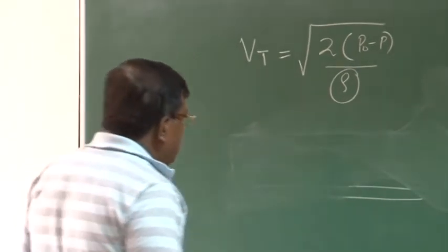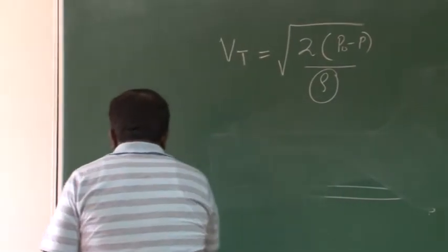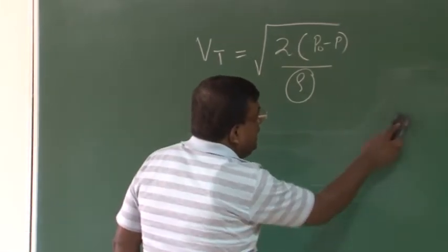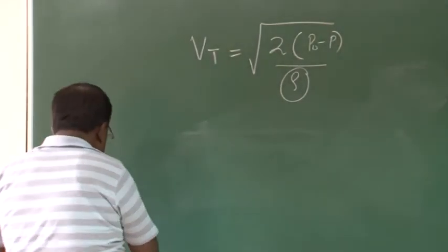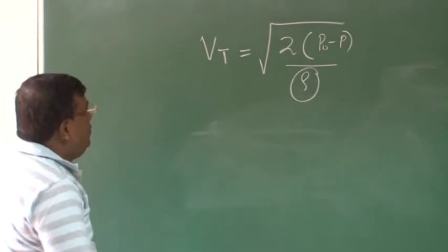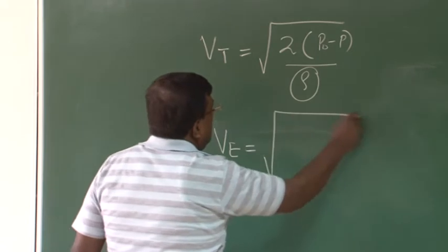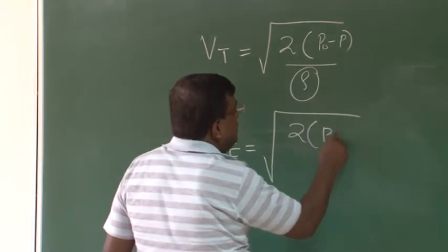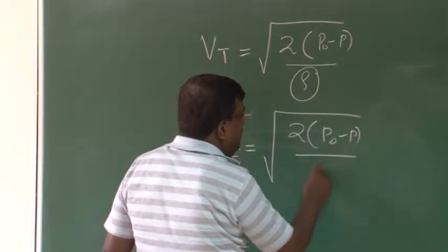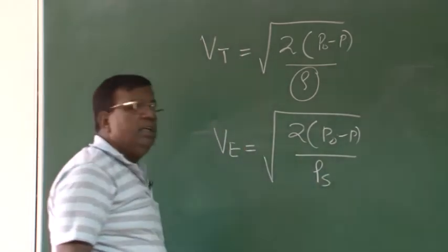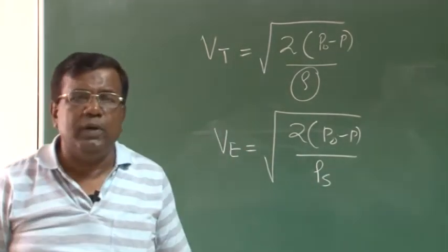But for calibration purpose, you could understand that getting density at every altitude, then calibration will be a difficult thing. So we have defined some speed V where this is the same dynamic pressure, however rho is rho s, which is the sea level standard atmosphere value.